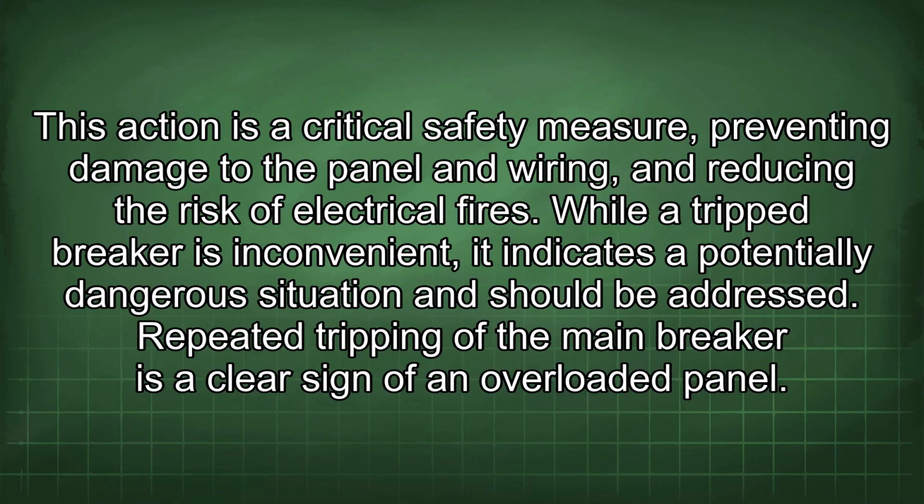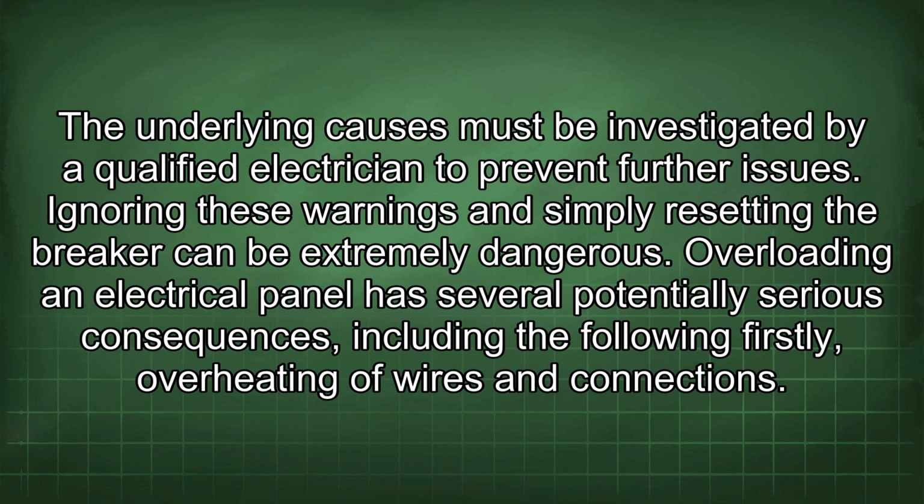Repeated tripping of the main breaker is a clear sign of an overloaded panel. The underlying causes must be investigated by a qualified electrician to prevent further issues. Ignoring these warnings and simply resetting the breaker can be extremely dangerous. Overloading an electrical panel has several potentially serious consequences, including the following.